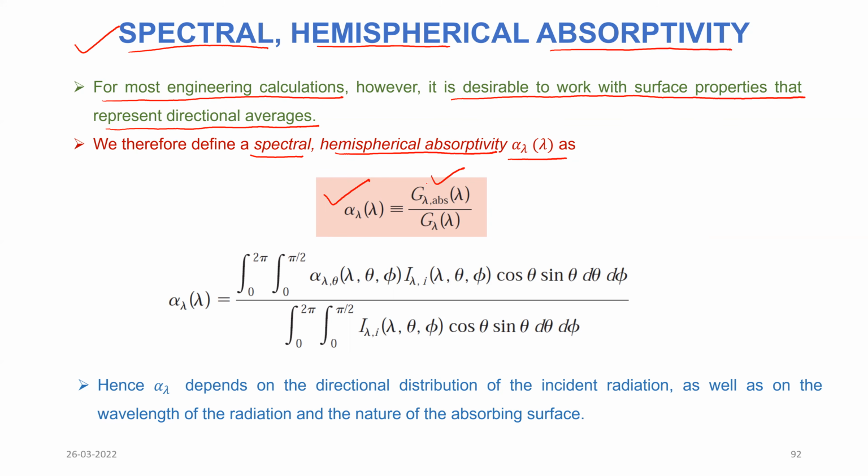divided by, so total incident energy or total irradiation which is absorbed, falling in a particular range of the wavelength, divided by the incident energy which is falling. So this is the absorbed part of the incident energy which is falling on the surface, and this is the total energy which is falling on the surface. So alpha lambda can be given as...